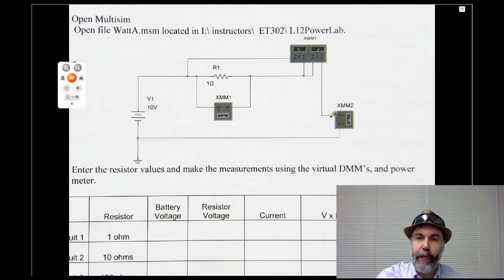Now let's look at this meter over here. Over here, the wire flows out of our resistor, and then it eventually connects over to this meter here, and then from that meter it goes on and connects back to the other side of our power supply. So in this case, we've connected the meter in series with our resistor.